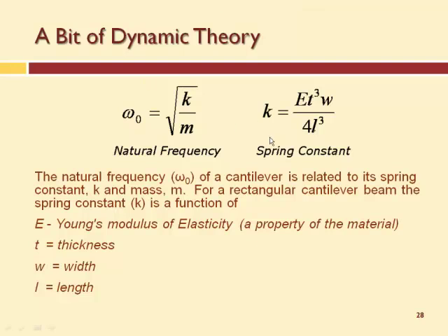It just depends what you want, where you want it to fit. You may not be able to make it really long in your application, so you have to make it shorter. So if you make it shorter, then you might have to compensate with the thickness. Okay, so if you want to keep K the same and L has to be shorter, then thickness has to be thinner. Okay?